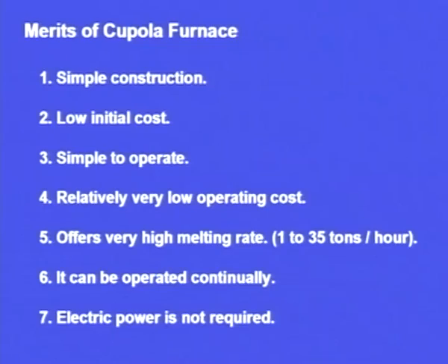So the furnace can be operated continually. Another advantage is electric power is not required. Especially in some places, at some times there is scarcity of electricity. So at that place, at that time, use of cupola furnace will be very good, because we do not have to depend on electricity.